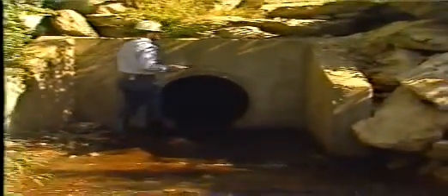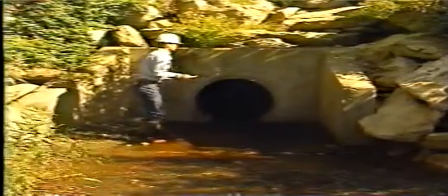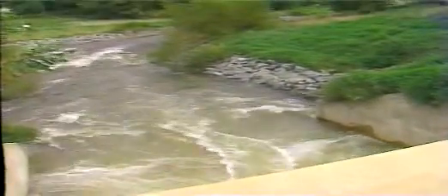Concrete spillways and outlet works can exhibit the same material deficiencies found in the body of a concrete dam, including cracking, spalling, pop-outs, pitting, and scaling. In addition, concrete as well as metal surfaces subjected to high velocity flows are susceptible to cavitation and erosion. Cavitation is a destructive process caused by the collapse of vapor cavities introduced into the flow by offsets in the flow path.